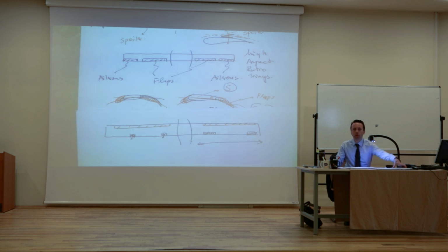Any questions? Yes, sir. Are these flaps on these notes actually helping with the CM alpha? Oh, what happens to the CM alpha? That's a very good question. CM alpha increases. It should be a negative value, but in the landing or during the takeoff, you don't want to actually do this motion. So you want a CM alpha bigger, right? Right, which means you really have to play with your horizontal tail.